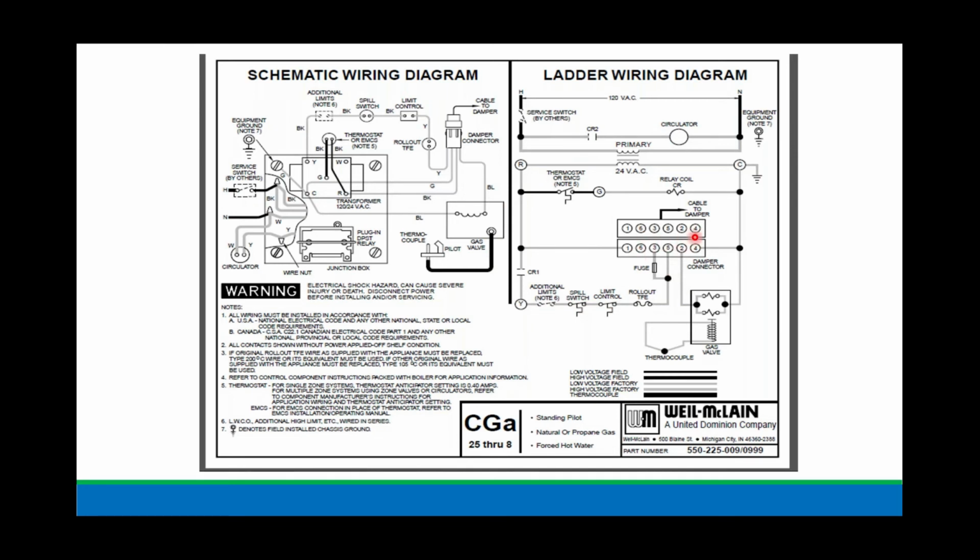You hear the vent damper motor open, and when it does, it will close an end switch, which will then energize the gas valve. There's two more coils in there. We energize those coils. They open the gas valve. Since you see thermocouple, that's our standing pilot, woof, we make a fire. It's as simple as that.